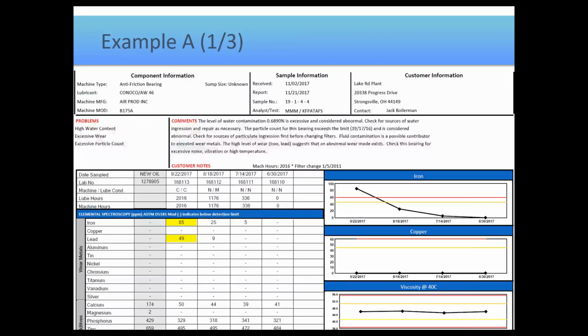Look at the iron count, look at the water count, look at the particle count, and just say, I can't leave this oil in service. If I leave it in, it's just going to get worse. And you know what? I agree with you. But here's where I can make my point really strongly. At the very beginning, I said, of the 3 steps you have to do a good interpretation, I said, read the whole report. But one of the things that we're adding to this is that we read every report. If we can read the whole report and get it done in 2 minutes or less, we now have the time to read every report. And out of the 3 most common mistakes I said is people ignore reports that come back normal. So here's my next question, and this is why I returned us to the first page of the report.